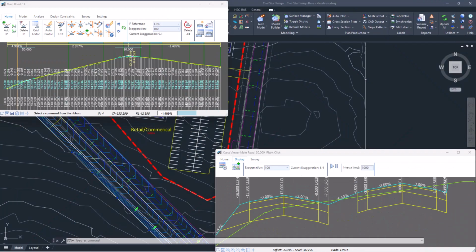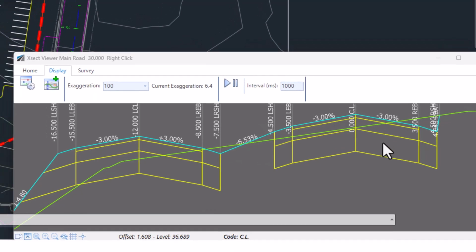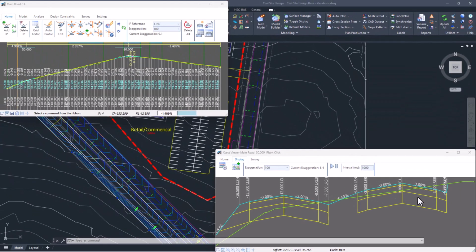So in a dual carriageway design or for other design scenarios, it may be desired to introduce a common ditch in between two codes. So if we have a look at this scenario, we have a dual carriageway with a dedicated design for what is the northern side of the road, and then a dedicated design of cross sections for the southern. And these are actually handled by two separate strings.